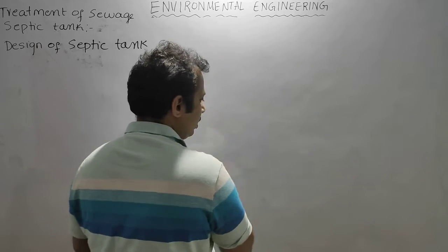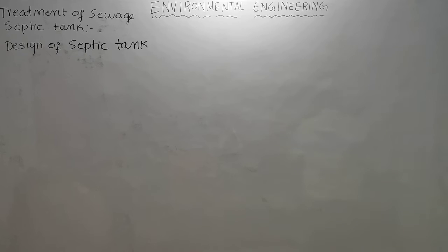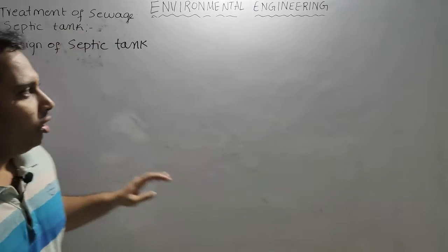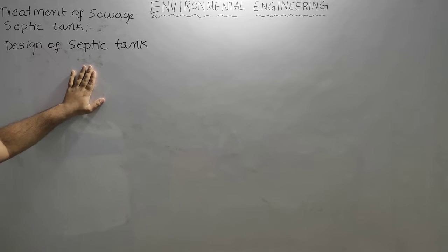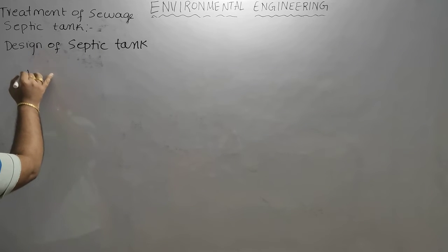Soak pit and dispersion trench, both are simply pits only. Trench or pit, both are the same. Okay. So one more point here. Before going into the soak pit, the total volume. We have found the volume of the settling zone. We have found the volume of the sludge zone. So what is the total volume of the septic tank?